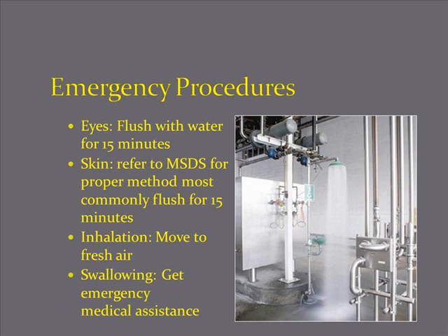Emergency procedures if you come in contact with chemicals. For your eyes, flush with water for 15 minutes. For your skin, refer to the MSDS. Most commonly, flush for 15 minutes. For inhalation, move to fresh air. Swallowing, get emergency medical assistance.